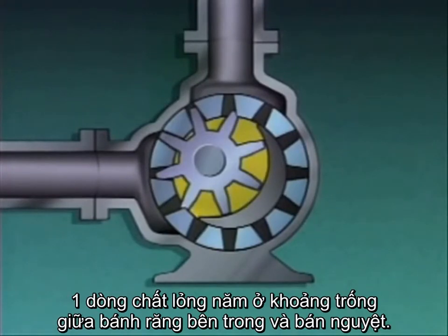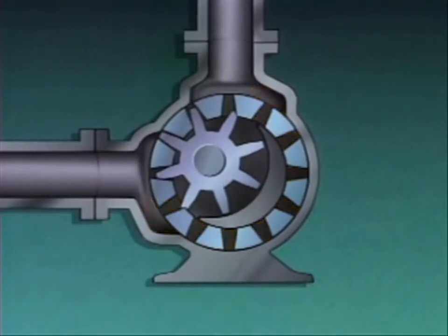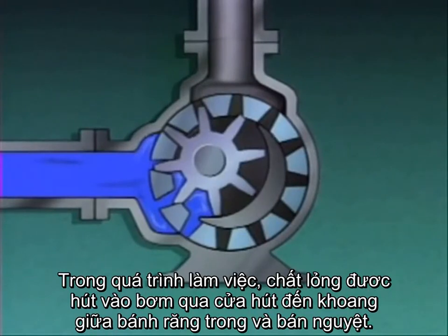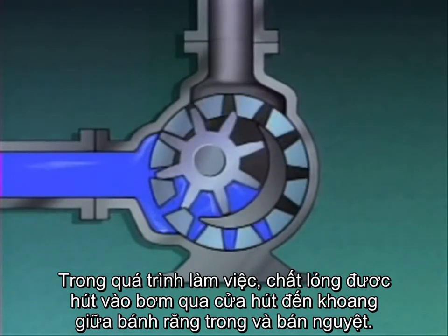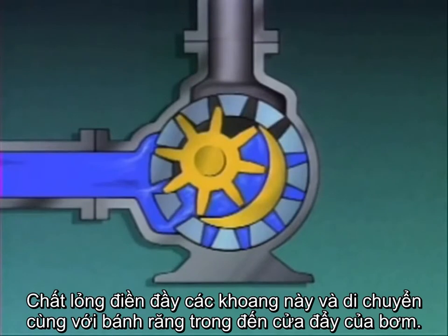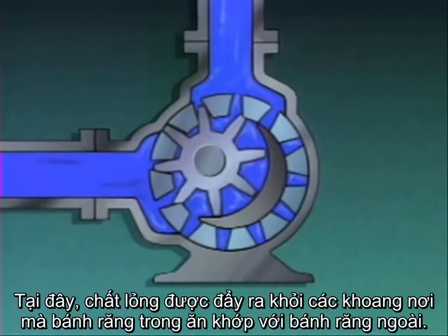One flow path is in the spaces between the inside gear and the crescent-shaped spacer. The second flow path is in the spaces between the outside gear, the spacer, and the casing. During operation, liquid is drawn through the suction and into the spaces formed as the gears unmesh. As the gears continue to rotate, the liquid moves into the spaces between the inside gear and the spacer. These liquid-filled spaces move with the inside gear until they reach the discharge of the pump. There, the liquid is forced out of the spaces as the inside and outside gears mesh together.